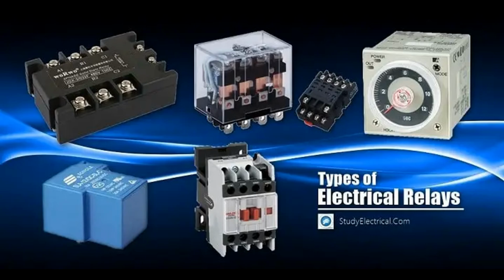Overvoltage protection. Relays are used for protecting electronic circuits and equipment from voltage spikes, surges, or transients that can occur due to lightning strikes, power grid fluctuations, or switching events. Overvoltage relays detect abnormally high voltage levels and trigger protective actions to limit the voltage or isolate the affected circuit. They may activate voltage clamping devices, such as metal oxide varistors, MOVs, or transient voltage suppressors, TVS diodes, to absorb excess voltage and prevent damage to sensitive components.